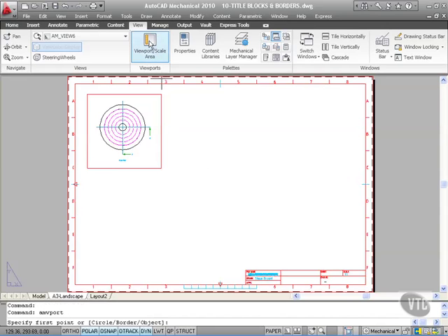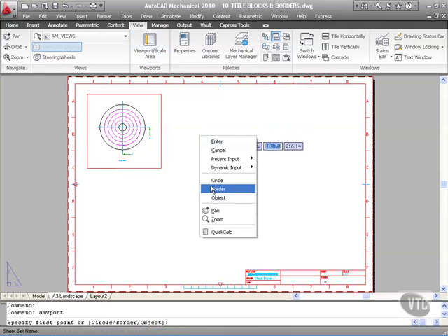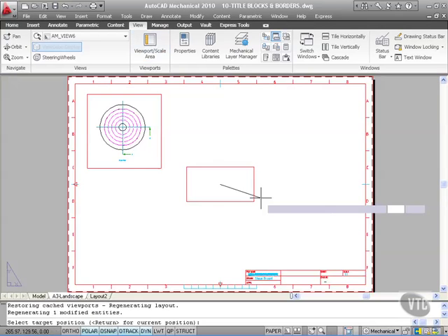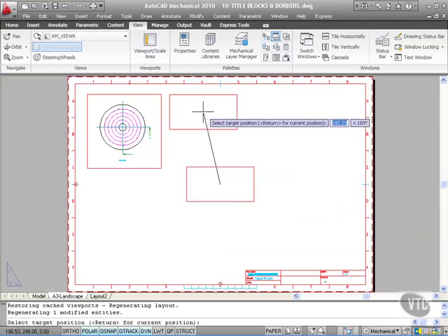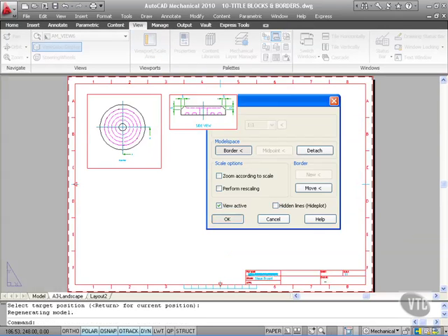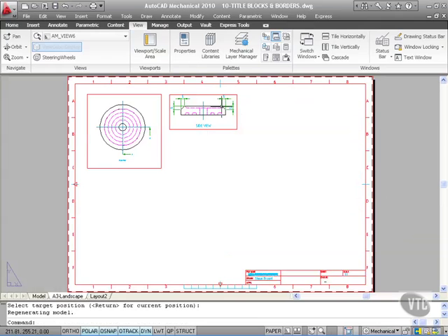So if I do another viewport scale area, right click, border, straight back in, I'll select this scale area here. I'll drop that one there. Just OK that now, and there you go. There's my side view straight in with a viewport at 1:1. Easy when you know how. So utilize your title blocks and your borders to make yourself quicker, more productive and more effective.